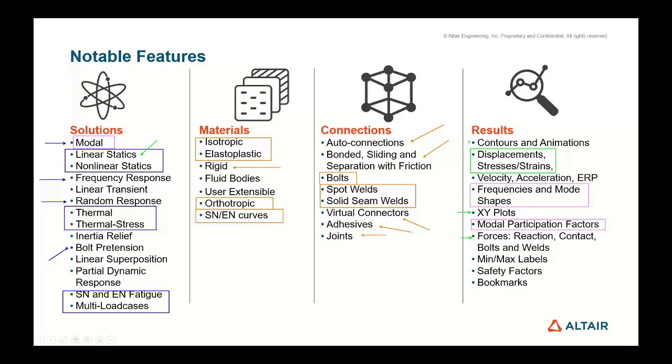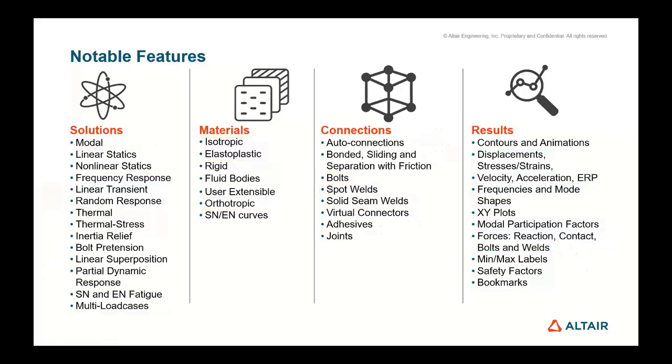I'll get my forces in my bolts, and obviously you can look at everything in terms of a contour and animation. And on the post-processing side, you can look at the minimum and maximum labels, safety factors, and bookmarks. So just so you know, in terms of the forces, such as your contact forces or the forces that are going through your bolts, you can always get these in the form of a table. So if you want to export it, and if you want to post-process it in Excel, you can.